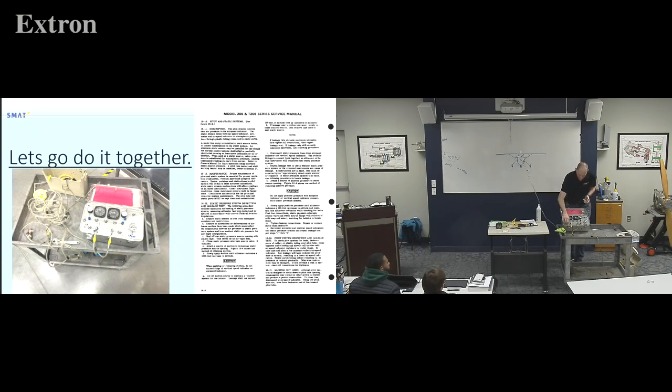Cool. Now our static system, we don't necessarily have to have this connected to our pitot tube if we're only going to 1,000 feet, but if we're going to go up really, really high, remember from our picture, our airspeed indicator in the aircraft, half is the static, half is the pitot. So what we actually do is we will open up this cross-feed valve. That basically bypasses our airspeed indicator diaphragm, so that both our pitot that I'm connected to, that we know is leak-free now because we already did the test, so our pitot and our static will be the same pressure. I'm not flying through the air, and that works.